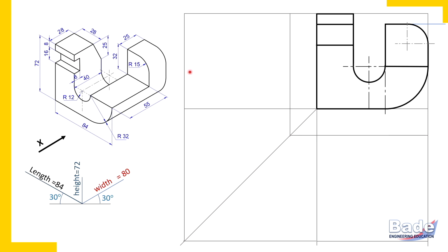Now tell me, is this diagram over? Not yet. Remember, right now we have thought about visible surfaces. When you draw a visible surface, automatically the corresponding edges will appear here. So if a surface is visible, that means all its edges are visible. So these visible surfaces and therefore visible edges we have completed. Now this is the front view.